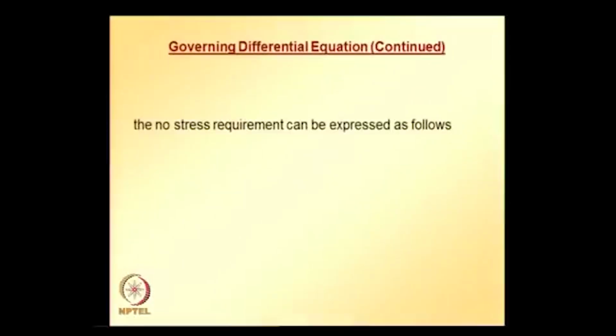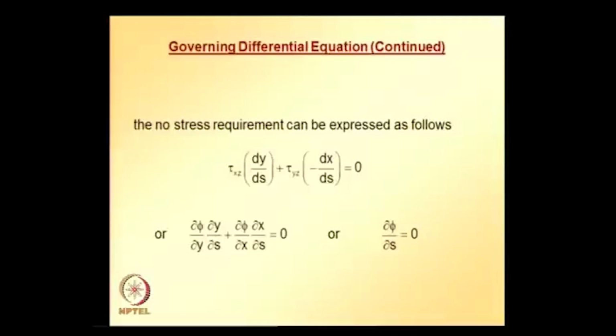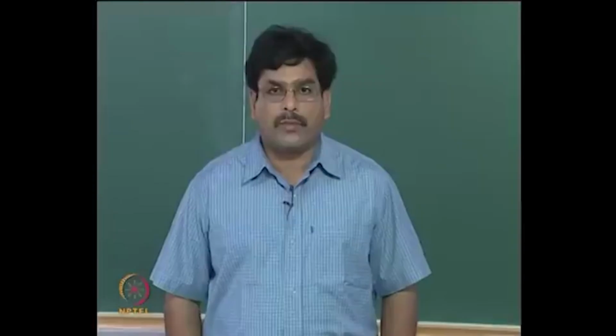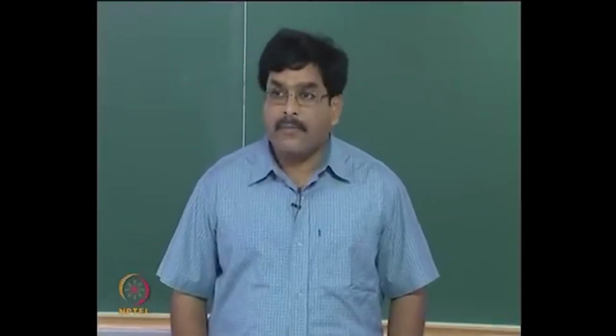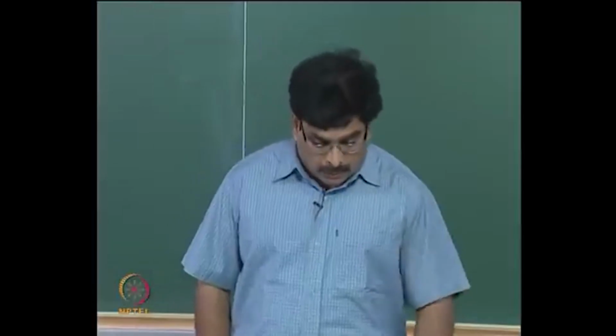The no-stress requirement can be expressed as follows. Here n_x and n_y are substituted, and substituting the stress components in terms of the stress potential, finally we get this equation: the partial derivative of the stress potential with respect to S is equal to 0.